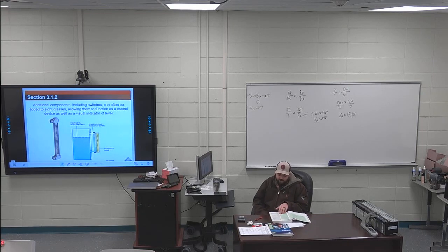Which is actually the second paragraph of 311. Got a little ahead of myself. Dipsticks and lead lines. It talks about checking the gas tanks for levels. I've got the second to last sentence in that second paragraph of 311 highlighted. Although this method of level measurement seems crude, it is accurate to about 0.1% with ranges up to about 20 feet. Out to the side of that, I wrote use to measure directly, using the stick.